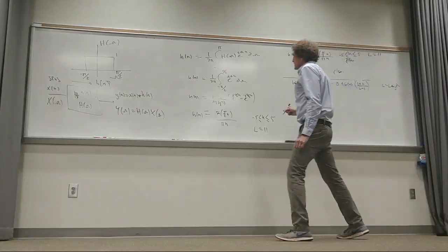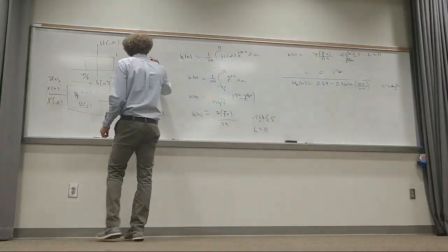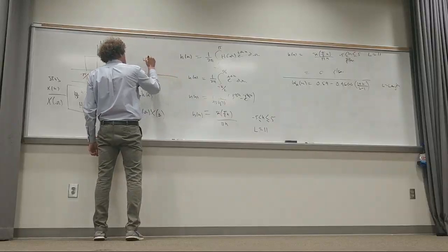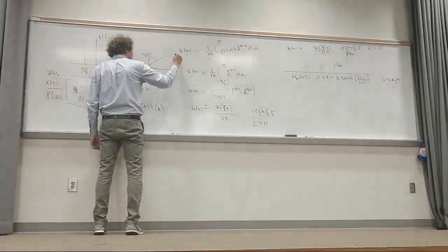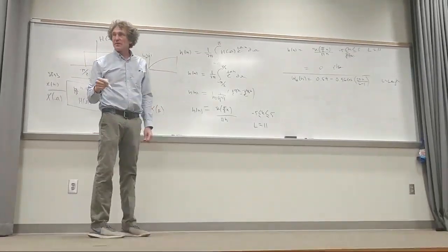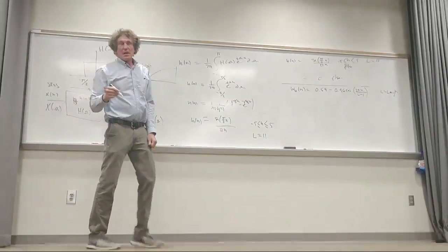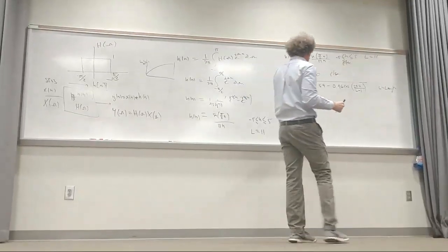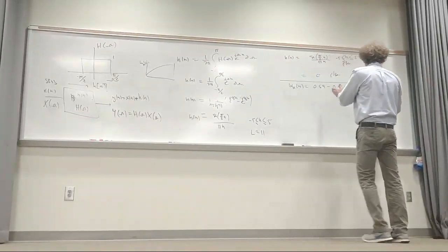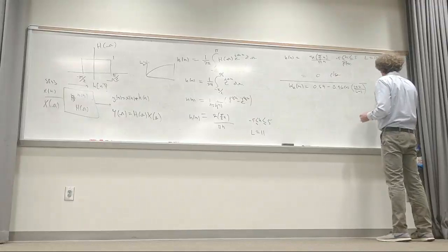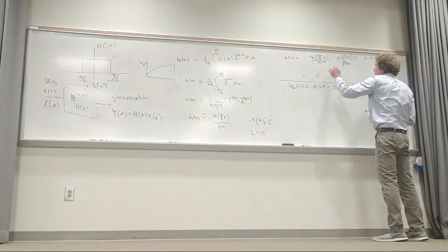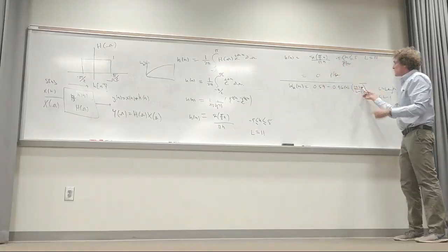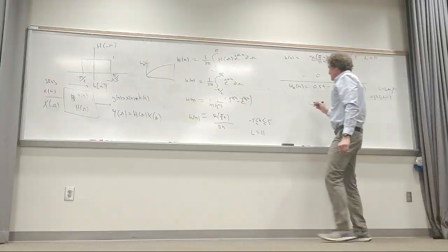So this is one of those functions, if I drew it here with the window, it starts like this, and it's basically like this kind of a window, if you take a look at it, right? So I take this, and now I have to shift this. This is going to be valued for n greater than or equal to 0, less than or equal to L minus 1, and I've got to shift it back to where this starts. That starts at minus 5, so I'm going to take n minus 5 here. This is how he does it in the book.